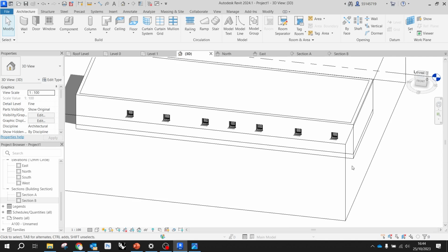So you can go and check all of these and say, instead of having the top constraint to be unconnected, the top constraint will be level 1. Say apply, and it's fixed. The only thing is, now with these ones, as we'll do later, we're going to select all of them, right? To select more, with control you have to select. All of these, you want to do attach top base, and click this one, and it will stop. And it will be constrained to that, right?